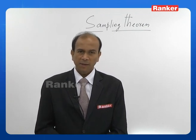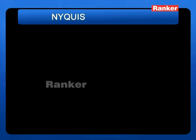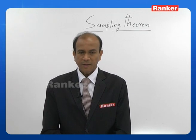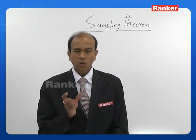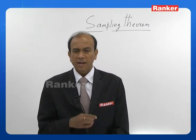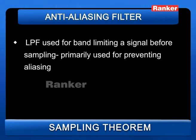I can oversample or undersample, but we should be very careful how much we oversample. Let us define the Nyquist interval. Nyquist interval is the time interval between any two adjacent samples when the sampling rate is the Nyquist rate. That is, the time interval between two samples is called the Nyquist interval.